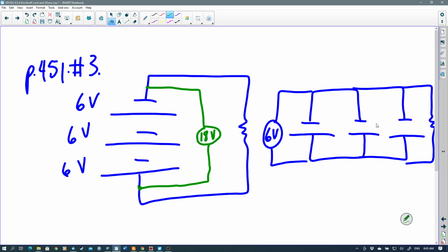For a parallel circuit, if you're measuring 6 volts on this battery, as long as all of these are 6-volt cells, by the way, because they're individual parts of a battery, you're going to measure 6 volts no matter where you are. So even if you measure what looks like the total for the entire circuit, as well as for this cell alone, it doesn't matter. All 3 of them are just going to give 6 volts.